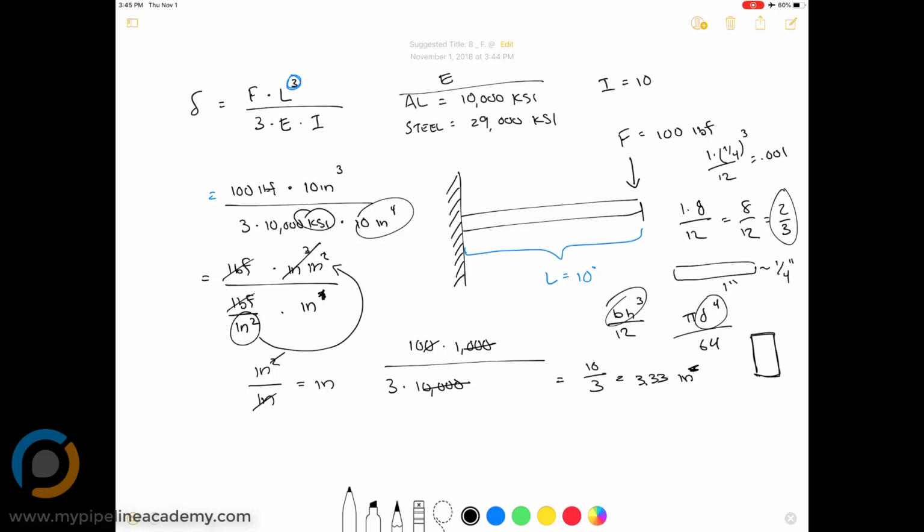If we ended up with something like, I don't know, a 1/4 of an inch of deflection, you know, that would be something that's very valid, because I'm sure a 1/4 of an inch out at a 10-inch length is well within the elastic range of an aluminum bar. And you can see how doing the math on this, it takes a little while, and it can be kind of monotonous. And oftentimes when you're designing something, you want to be changing really quickly.